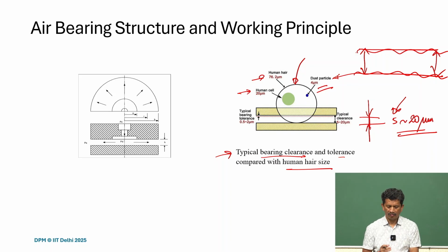Once we want to use this, we should be aware of that. What we also need to understand is that air is fed to the orifices, then simply passes through the bearing surface to atmospheric pressure. So it is always a positive pressure most of the time, unless we are using some kind of vacuum preloading. We will talk about preloading.